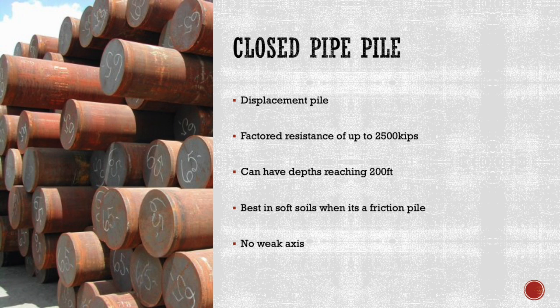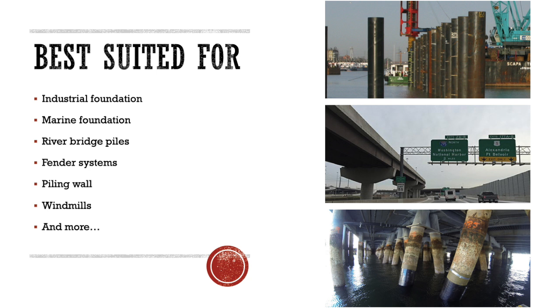This pile also has no weak axis. Pipe piles are best suited for industrial foundations, marine foundations, river bridge piles, fender systems, piling walls, and windmills.